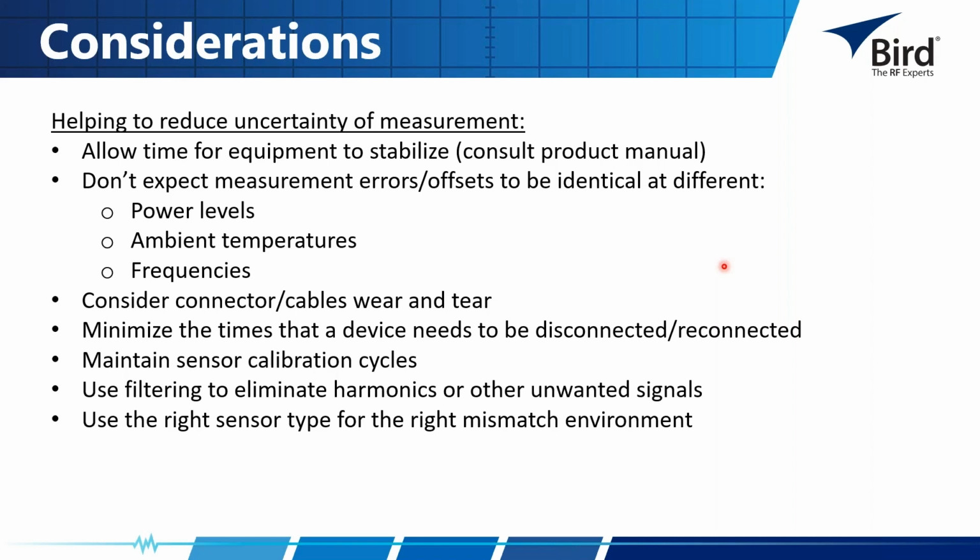And even when we're thinking frequencies, we could think of the image of the antenna where we had a frequency sweep and we were seeing the VSWR values over a larger range. So make sure that the performance is going to be what you desire at your particular frequency. You might have some variation even over a performance band that you're looking for.